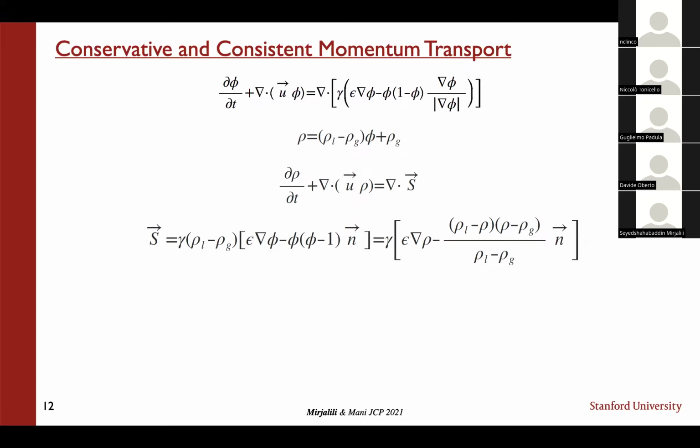The first thing is, can you provide details about the pressure-velocity coupling in your solver? And also comment a bit on how you selected this source term S. When you adopt central differences, the operators need to be skew-symmetric.